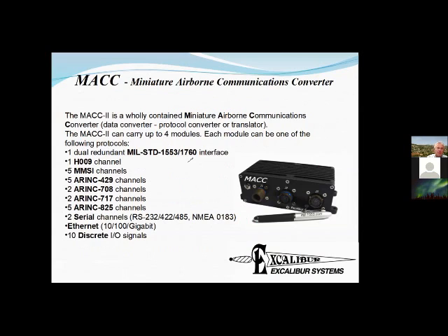In fact, here it is. So there, what we talked about a minute ago was translating ARINC-429 to ARINC-429 with just a tweak. But what if you got say a helicopter, which has been built completely with 1553, military helicopter, everything in it is 1553. And one of the boxes in it has gone obsolete, and you need to upgrade to a different box. Now, in order to upgrade to a different box, you got a lot of stuff to worry about, right? It's got to fit in the same space, right? So that's form.